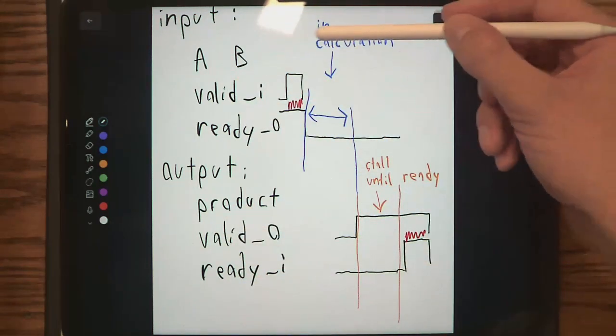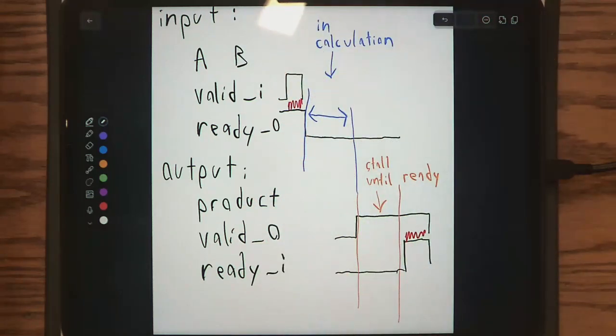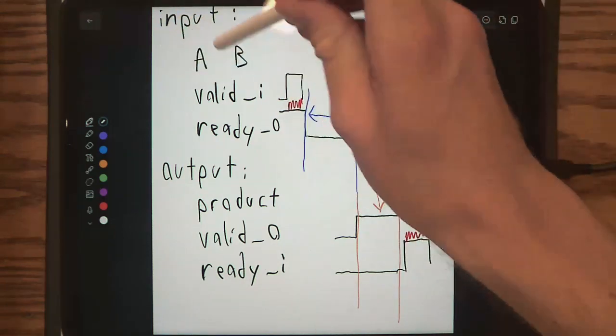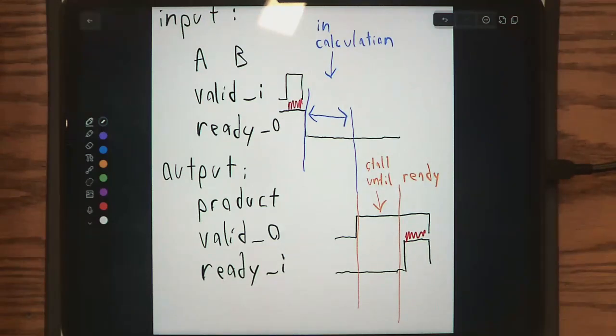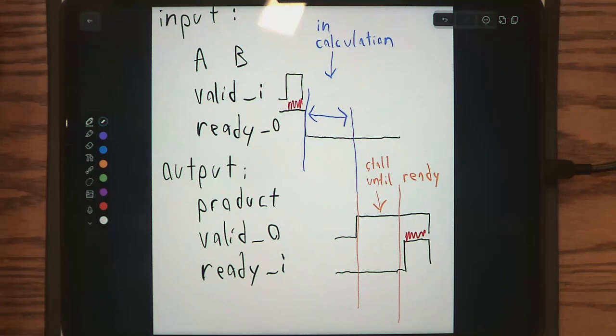And then you also have your ports here. If you've heard of parallel communication or a parallel interface, this is a parallel interface because we are sending the entire width of A and the entire width of B all in one go. This would be separate from a serial communication where maybe you sent each individual bit of A and B one after another. If you are familiar with USB or SPI or I2C, there are a lot of different serial communication protocols that involve sending one bit after another. In this case, we send the entire signal all in one go.